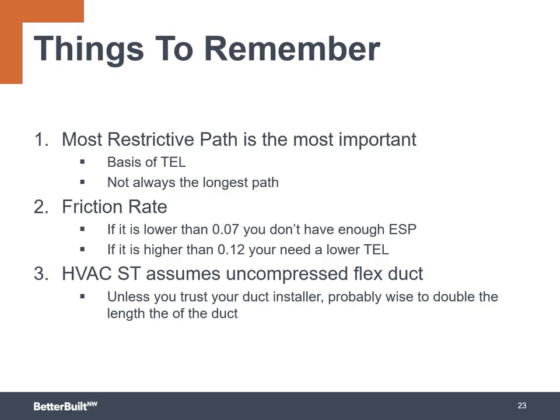So if I'm looking at a 15% compression, does it look compressed? 15% sort of looks like the Loch Ness monster, and the owner of the company might not trust their employees with duct knives. And 4% looks like someone yanked the heck out of it. 4% is perfect. When I see 4%, people have made their best effort to pull it tight. They're using Panduit straps on the end, and it's a thing of beauty. Cool.